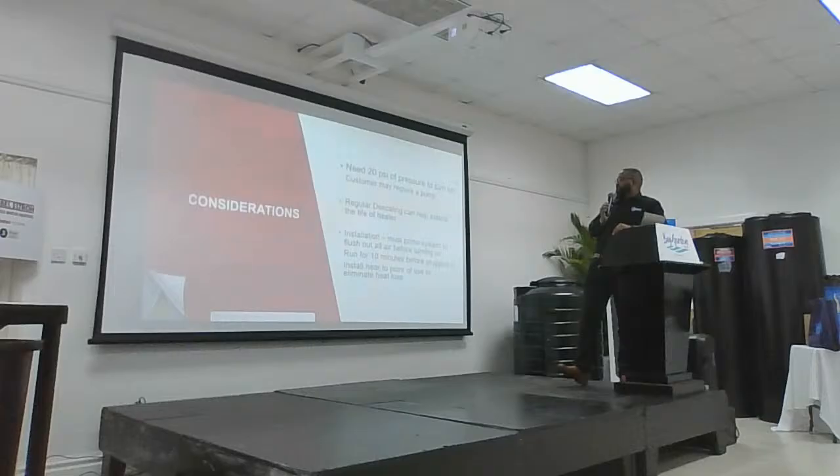Installation: must prime the system to flush all the air before turning on the unit. Same thing I said earlier, because if not, the unit, if it has air detection, will trip off. If not, it could lead to the unit dry running and burning the elements, right?